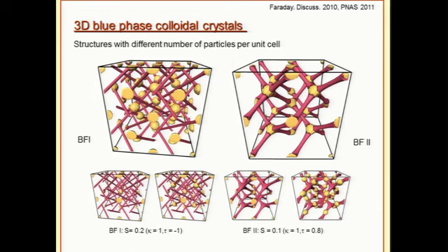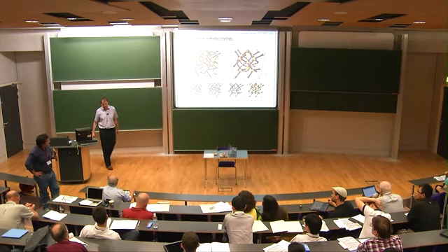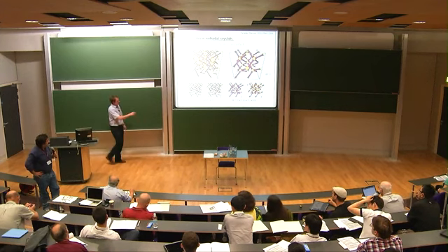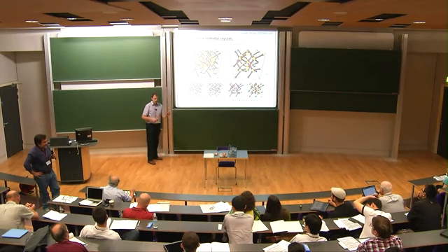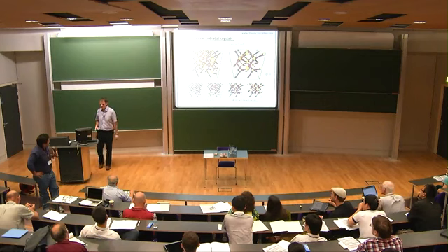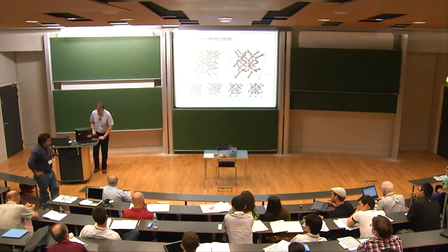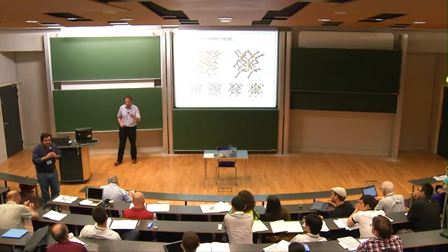I mean, the question is actually very relevant, because what might happen is that you get pinning of defects if your mesh resolution is too small. We checked this. Yeah, it works. We are very careful about this. We are just at the border. If you go to a mesh size of, say, 30 nanometers, then I'm not sure anymore. You will get the results, but the results will be wrong. Yes, exactly right. We are very careful about this.